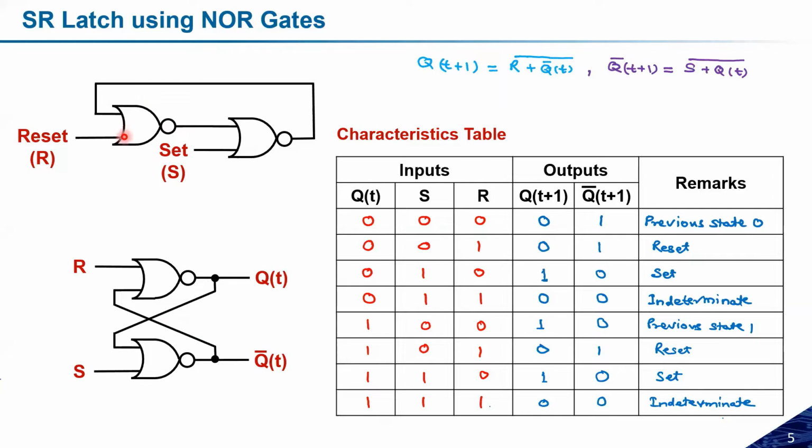You can design an SR latch either with NAND or with NOR. Both are possible. These two additional inputs are utilized to trigger this logic, and we call them the set and reset inputs. Based on these, we prepared a characteristics table, which looks like this. From the diagram, we can see the equation Q(t+1) = S + R'Q(t).